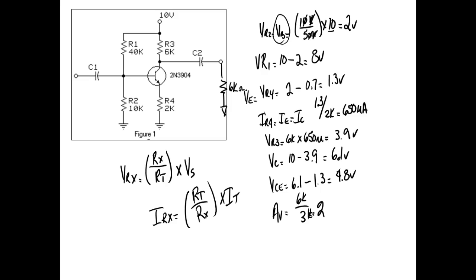And we're not going to have an amplifier if we don't load it. I mean, it'd be stupid for me to have an amplifier that I don't hook a speaker up to or something up to, right? You understand? So what I just did is I loaded this amplifier with 6K. Now, it can be anything. It could be another amplifier stage. It could be something out there, but it's going to represent an R value, right? You understand that? So what would we expect to happen? Would we expect that gain to go up or would we expect the gain to go down?